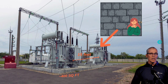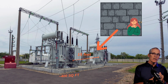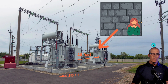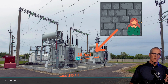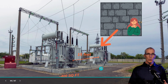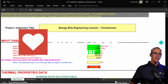Here we go. We put in 2 transformers to try and account for one of them failing. Now, what if the one fails and takes out the other? Could that happen here? Well, we don't have them in the same pit, or the pits are far enough apart. Well, if we've got a 400 square foot pit and we go from the center to the edge, we've got about 15 feet of separation, right? Because we don't go from the edge of the pool to the edge of the pool. We go from the center of this pool to the edge of this pool. So we're really only looking at about 15 feet of separation.